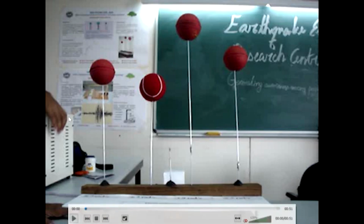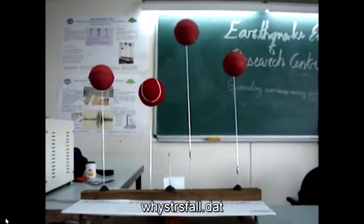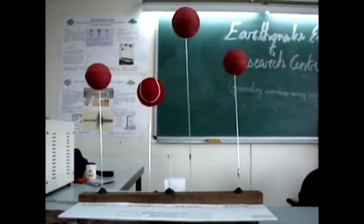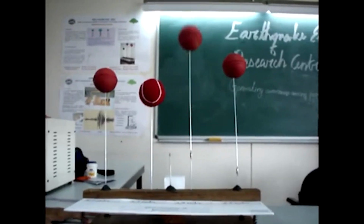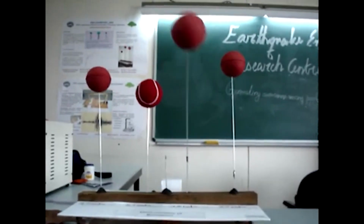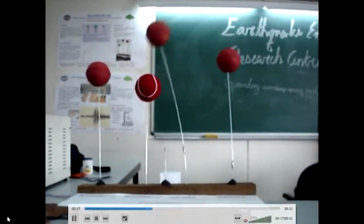Let us look at it. Now, as you can see, a slowly varying acceleration, that means a slowly varying force, is applied. Because of which the excitation frequency is matching the natural frequency of the tall building. That is why the tall building is vibrating violently, with severe motion and severe displacements.